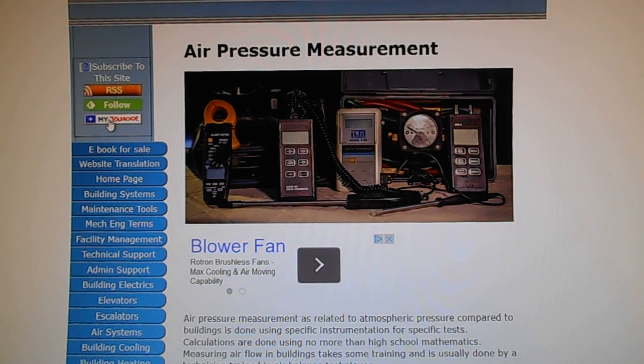When it is noted that airflow as produced by a supply, return, or exhaust fan is below design parameters, adjustments will have to be made. Whether fan motors and blowers can be increased in speed is dependent on the horsepower of the motor that is in place. If there is sufficient amperage draw available on the motor, it may be sped up proportionately. To increase or decrease fan or blower speed, the fan pulleys will have to be changed.